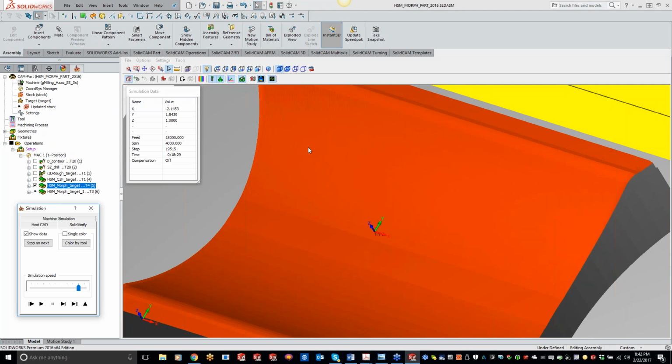It's a hydraulic style holder, so it clamps evenly around the entire outside, versus a set screw, where even though it's a pretty tight fit, it is pushing it off just a little bit. So that could be part of your problem too, Jason. Maybe you just have an out of balance, but the bull nose should give you just as nice a finish, not having that ball at the very bottom.